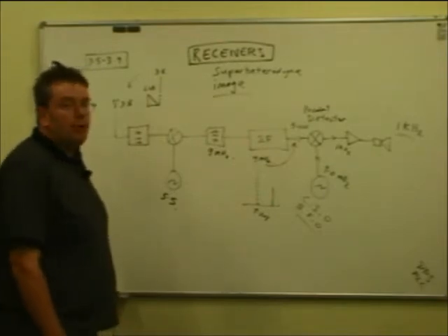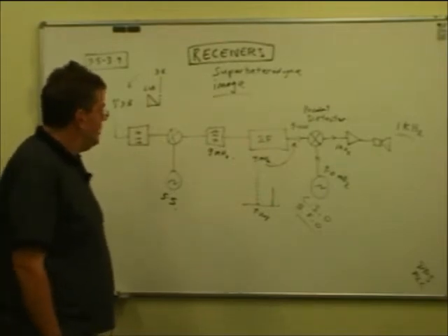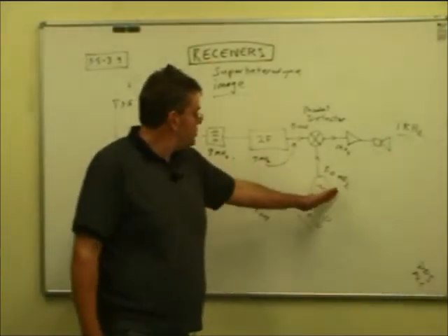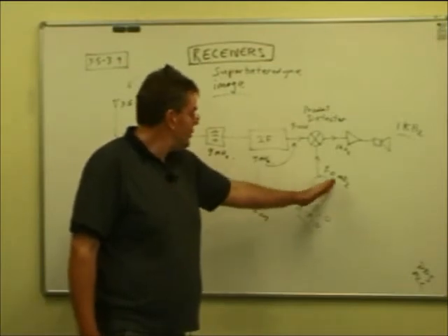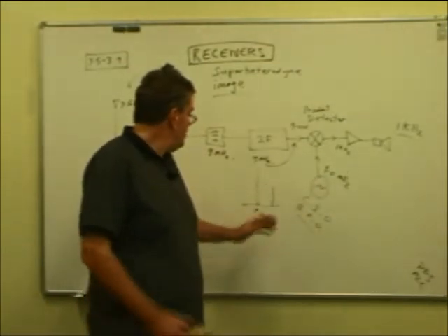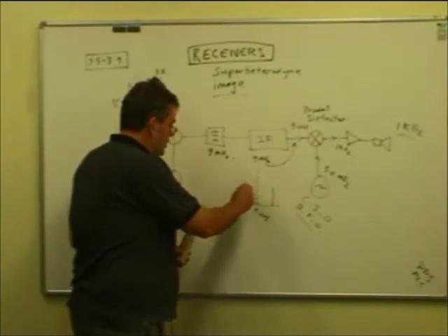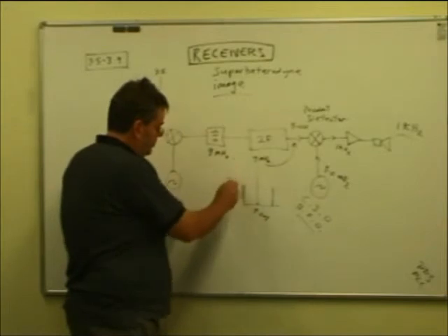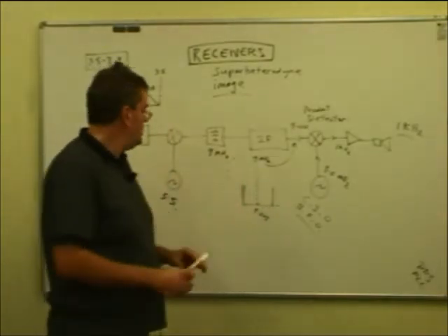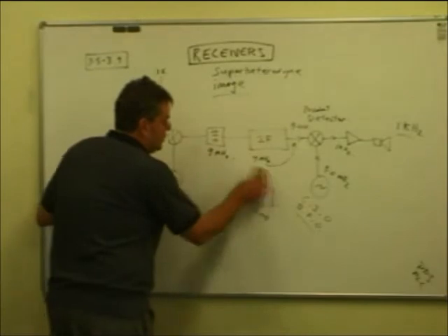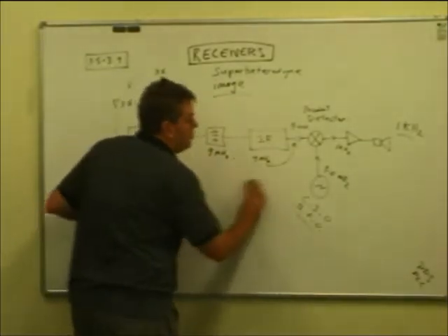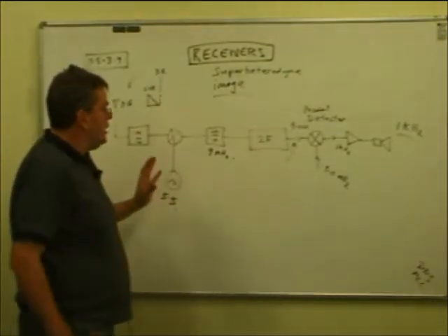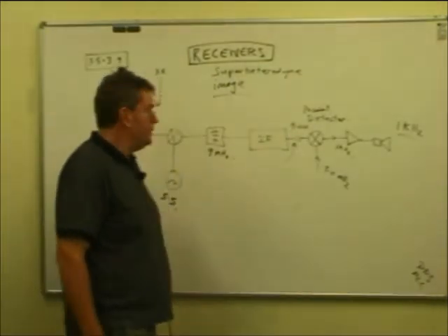If you want to receive the upper or lower sideband, we won't go into all the details, but there's several ways you can go about it. Commonly what we would do is just switch between two carrier frequencies here. So if it was the other sideband, what we could do is inject the carrier at that point there and get the sound out. If you want to read more about that, it's quite well explained in all the texts. It's just a simple way of shifting the carrier insertion oscillator.